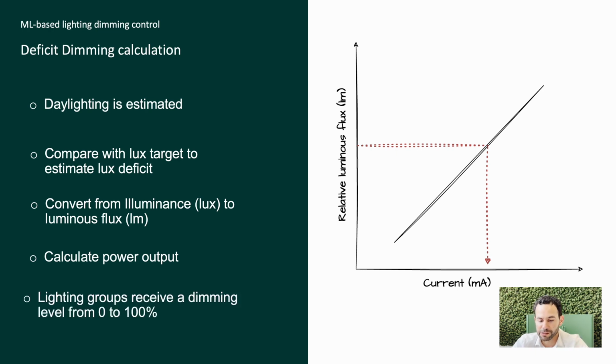With that information, it is possible to estimate the right dimming percentage to meet those 200 lux. This process takes around 200 to 500 milliseconds per space. This is quite important, to keep it very low latency, meaning that it is possible to estimate any number of lighting controller groups, because this process is highly scalable thanks to the properties of machine learning model prediction infrastructure.